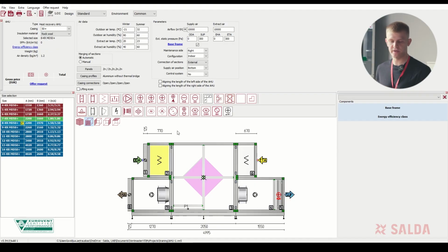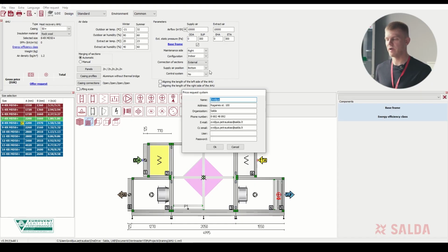To select a ventilation device, we first need a request formulated by our client or designer. What request I choose for the ventilation device, you now see on your screen. Before starting to select a ventilation device, we must perform a very important step. On the left side of the window, clicking Extra, Connection Settings, and Login allows us to log in with our details.